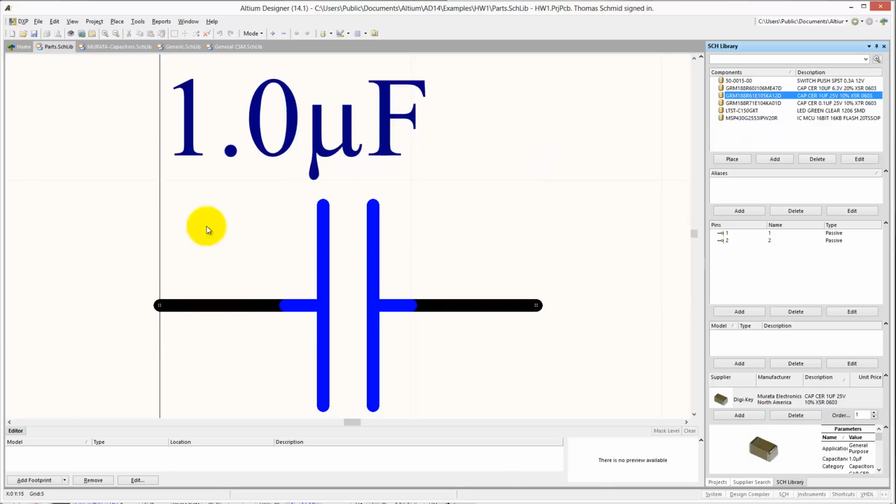Well, the schematic is a representation, a symbol for the actual part that you will use, and we will later on use that schematic symbol to create a functional schematic on a sheet. The footprint itself is its physical instantiation, which will be the part that is actually physically placed on the board and that we will later get manufactured. So in order to create the footprints for the different parts, we need to get to the data sheets and figure out what the footprint has to look like.